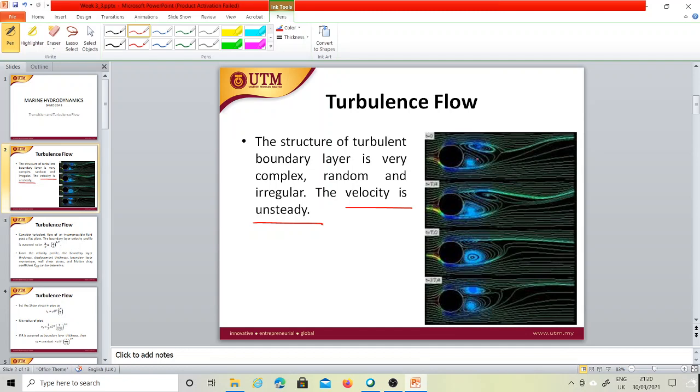Okay, so this is just an experience from the wind tunnel. If you have a cylinder or any spherical shape, then beyond it, as you know, at this point the separation will occur, right? I already explained this in my last video, how the pressure changes and how the velocity changes. At this point you will have zero velocity. It means the flow will separate from the body, and after that there will be negative pressure, right? Due to that negative pressure, there will be some space where we will have a vortex. Okay, so we will have the eddies, which circulate the motion at this point.